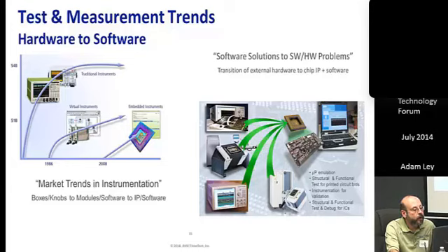Of course, with the structural test methodology, if you have access to physical test points, you might be familiar with in-circuit test. But as the circuit boards become more dense, the possibilities for physical test points and probes become diminished, and that gave way to what we know as boundary scan, which is another form of embedded instrumentation.